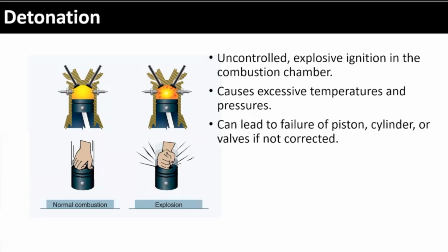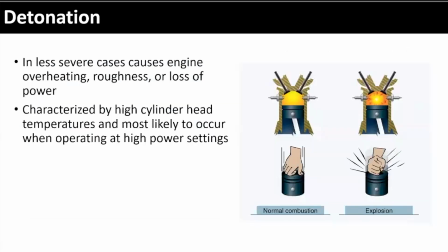We talked about this when I first mentioned the grades of fuel, right? If you're burning a low octane fuel in a high performance plane, it's burning too hot, right? You're going to have that kind of detonation. You want the right kind of fuel because the manufacturer has built that engine to run smoothly through those four strokes, to make sure they don't have that detonation. Okay.